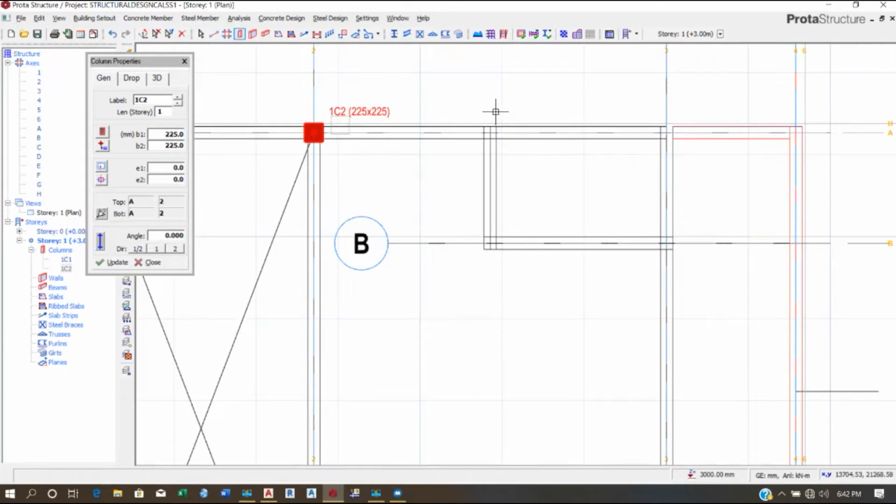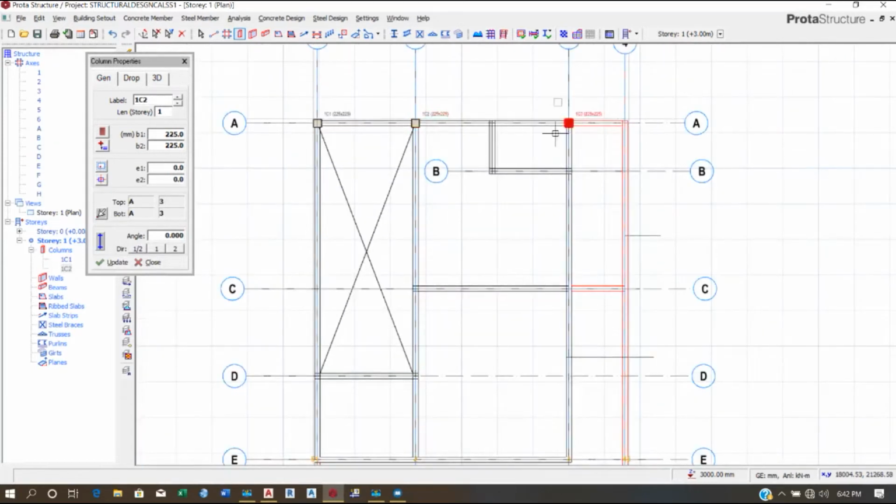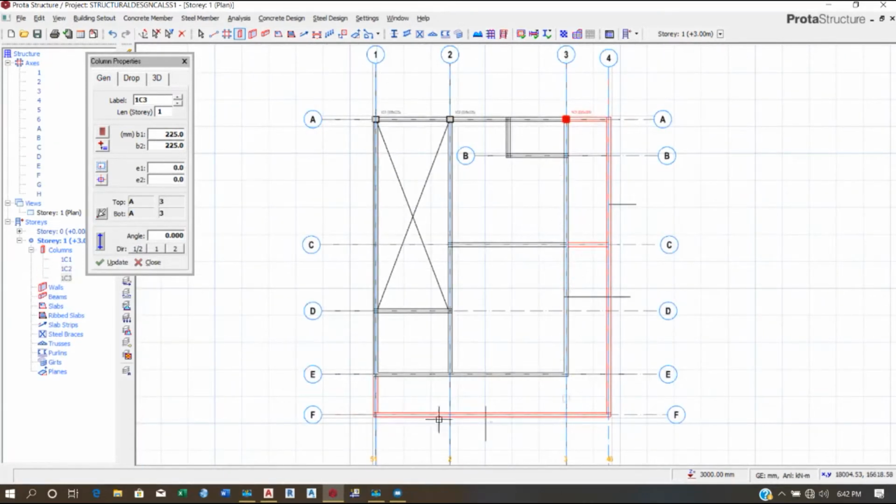I have staircase here. So remember, this is our cantilever, so it's above. So this column is beneath the floor, so we don't need a column there. Yeah, I need a column here, a column here, and I need one here. This staircase, so my landing is going to be somewhere here. So this column will sustain the landing. So I'll press close.